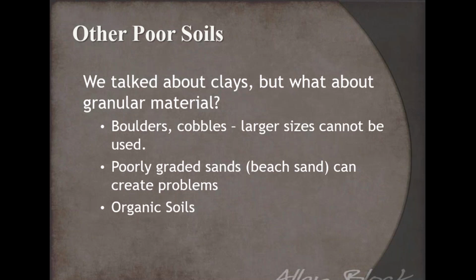So on the design side, what we do is we just encapsulate that material with a geotextile or a fabric, so that way it will stay in place and perform just like we want it to. So anytime we're dealing with poorly graded sands, we're generally recommending some type of fabric to encapsulate that, which is one of the few times we do recommend fabric vertically behind a wall. Normally we're just talking about the geotextiles horizontally.